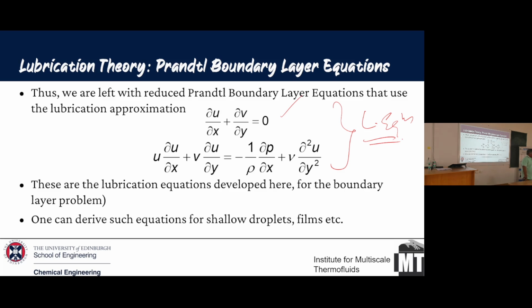Yeah. So that particular case, you did the experiment also, right? Yes. And how did you suppress the instability? You mentioned something like that in passing. Yeah. So you mean those hydrothermal waves? Okay. One way you can suppress the hydrothermal waves is by altering the system parameters. So the Prandtl number is typically used. Prandtl number again is a property of the liquid. Okay. The other way is looking at thermal Marangoni.